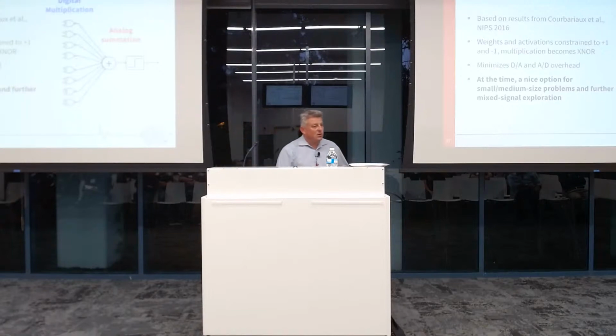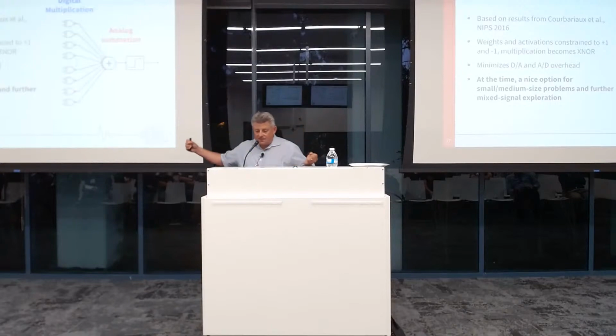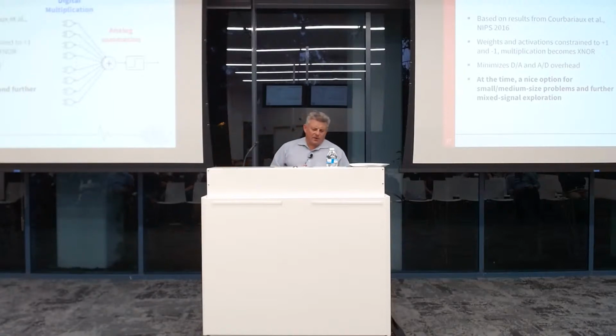And that's really cool because the multiplication is then efficient. And the only thing that remains as maybe an efficiency ceiling is the addition. And this is where we then added the analog idea in. We then said we're going to make a lot of small caps, and we're going to do the addition by charge sharing with very, very small caps. So I'm going to show you what this looks like in more detail, but that was the idea.